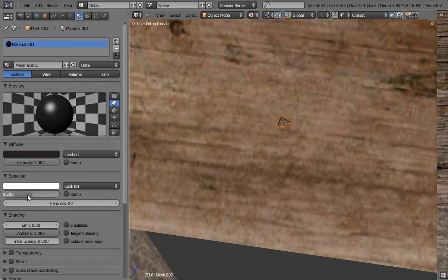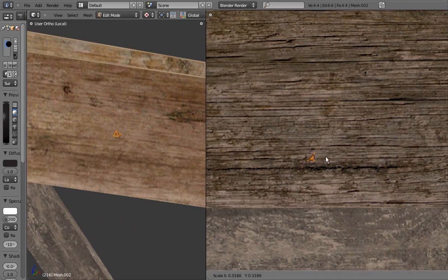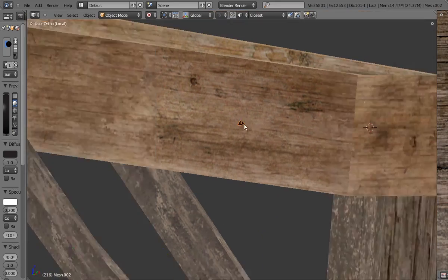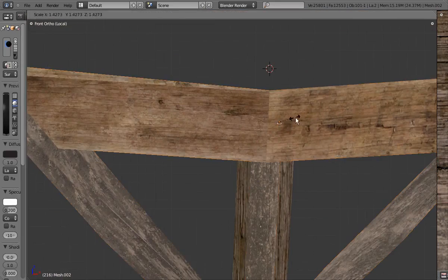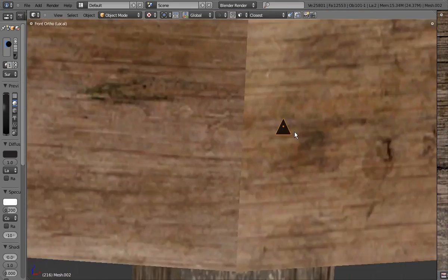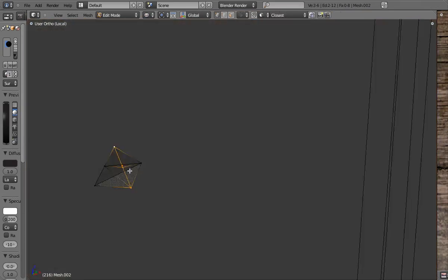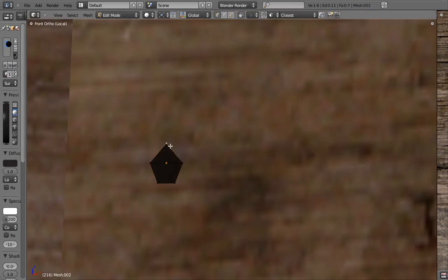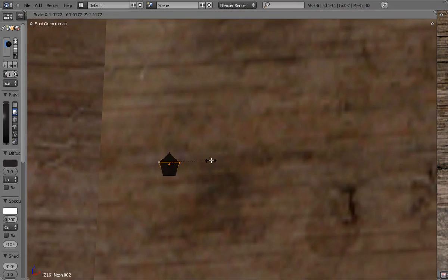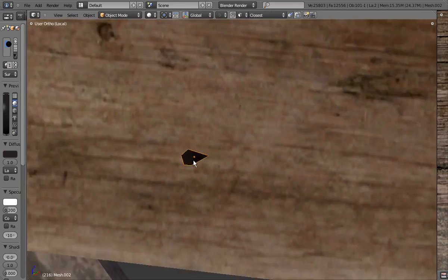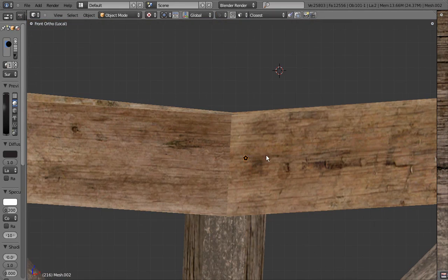In order for the shadows of these tiny nails to appear on the AO maps and the shadow maps, I would have had to have rendered the AO maps at a much higher resolution than I do. And you can do that if you choose to. I just end up keeping these in the scene. It just adds a little bit of extra detail. They don't look that great, but it's something. The idea was just to have their shadows on the texture maps, and that way it looks like there's nails there, but I end up just keeping them there.